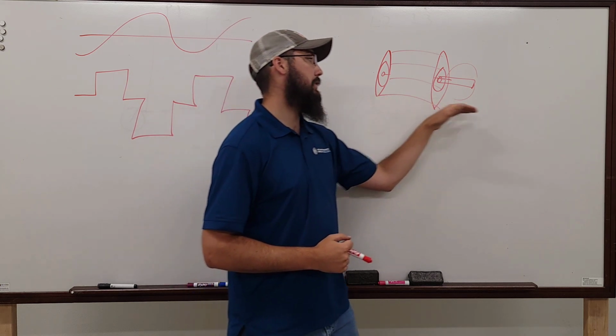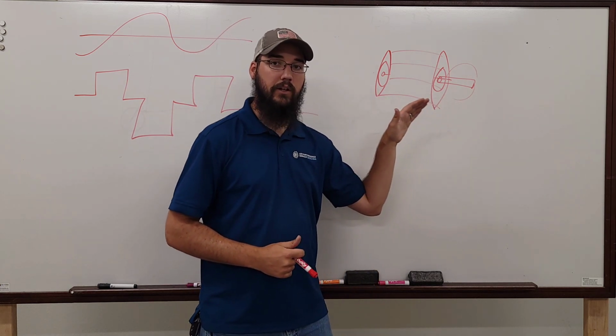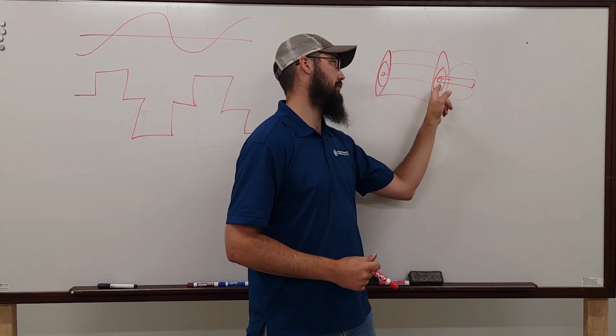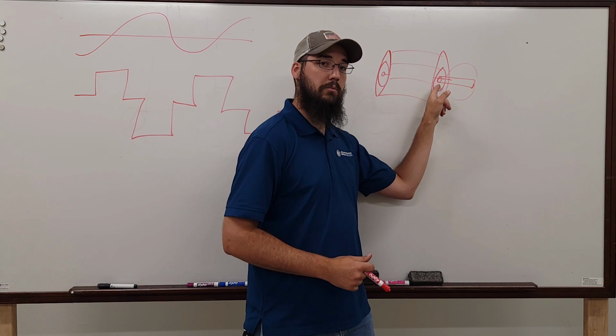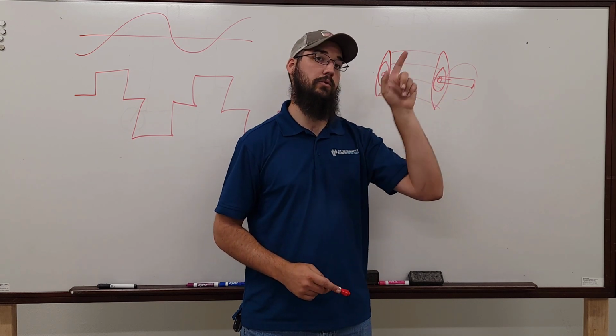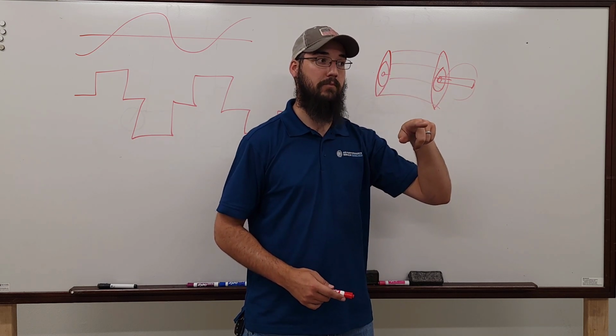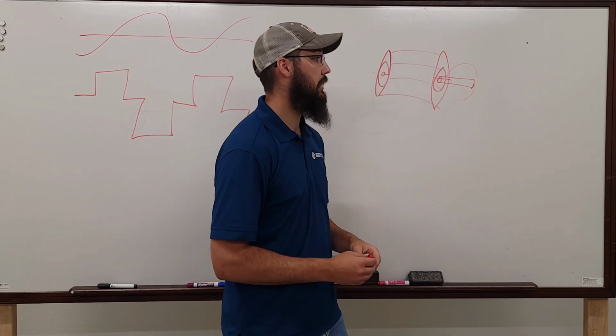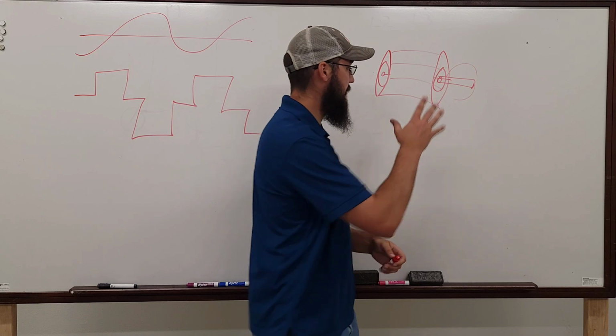I was going to say, if this was a direct drive, you have less of an issue, but actually you don't, because even if it doesn't discharge through the motor bearings, it'll still discharge through the blower bearings. So even a direct drive doesn't solve your issue. You still have the same problem.